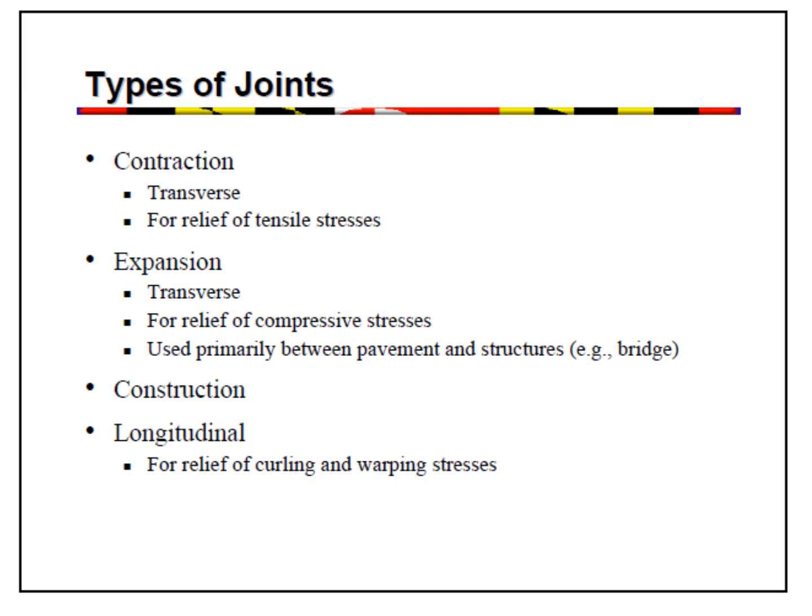Contraction joints are the most common type of joint in concrete pavements. Thus, the generic term joint generally refers to a contraction joint. Contraction joints are chiefly defined by their spacing and their method of load transfer. They are generally between 1/4 to 1/3 times the depth of the slab and typically spaced every 12 to 50 feet, with thinner slabs having shorter spacing.